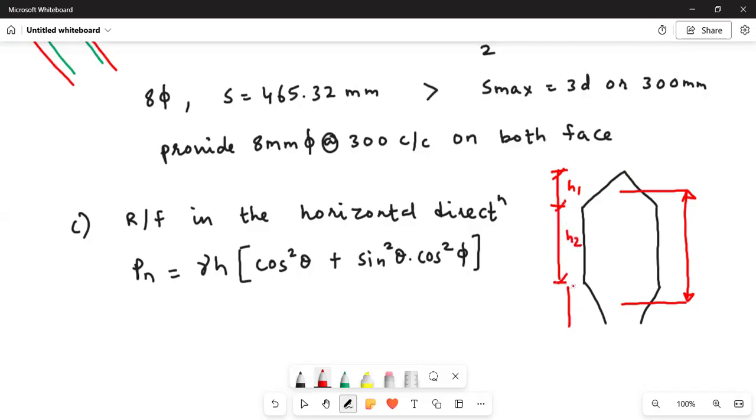And this is H3. Okay. So why do we have to take half? Because the material is not constant. It is a triangular shape. That is why we need to take half. H1 divided by 2 plus H2. We need to take the entire H2 because H2 is just like a rectangular portion, plus H3 by 2. So that is your H.